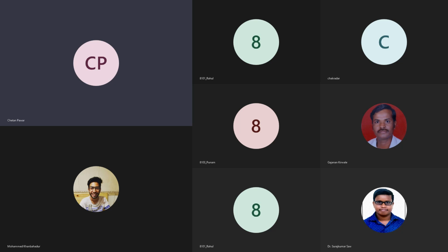Okay, Mohammed, have you selected the drain terminal or the source terminal? Maybe you have selected the source terminal, right? So this is your source current, okay? And you need to select the drain current. Drain current means the bottom terminal is the drain.